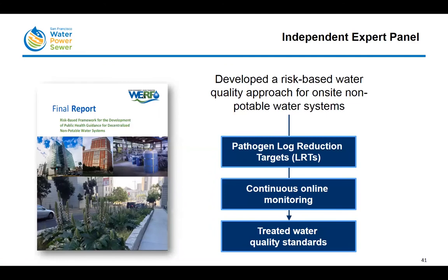And so what we decided to do was to put together an independent expert panel of water quality specialists to really address this issue: what is the appropriate water quality standard for decentralized on-site treatment systems? And what came out of that process was this report. And this report really laid the foundation for the risk-based water quality approach. And so it established pathogen log reduction targets for virus, protozoa, and bacteria. It established continuous online monitoring regimes, and really led to treated water quality standards from a risk-based perspective.